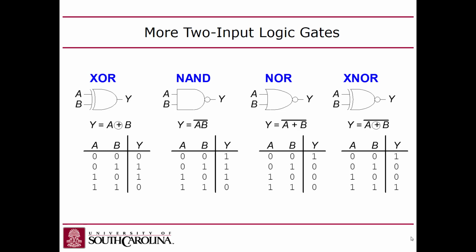Now, the disadvantage of the truth table is that it is going to grow exponentially, right, with the number of inputs. So these truth tables are manageable because it's 2 inputs, so it has 2 to the second power rows, right? But if you have a circuit that gets up to even 5 inputs, right, 5-bit inputs, that would be 32 rows.